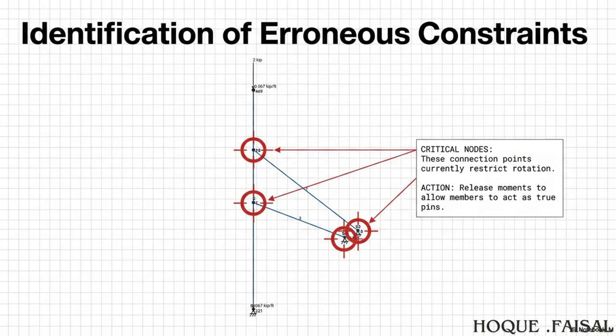It would be more accurate, yes. If you weld a joint, it becomes rigid. It can resist a bending moment. So if you actually built it that way, the structure would be incredibly stiff. It might actually deflect only 0.077 inches. But nobody builds temporary formwork that way? No, of course not. This stuff is temporary.